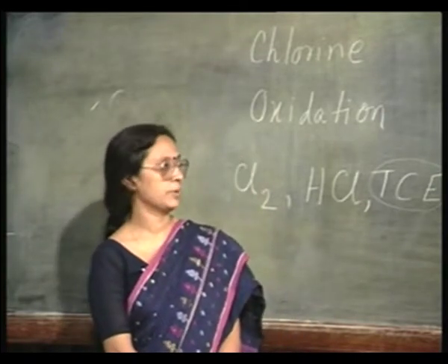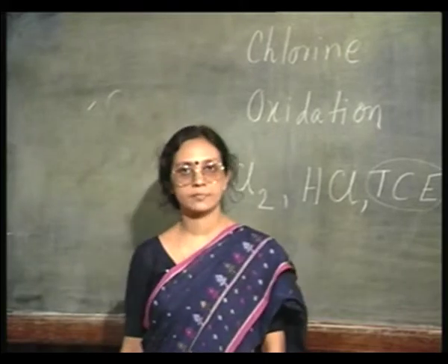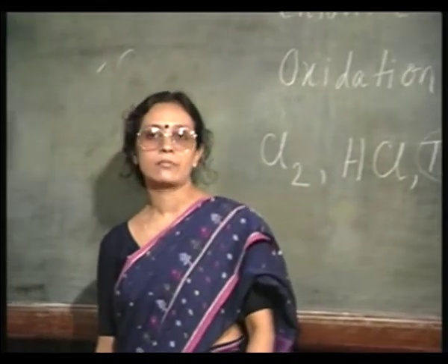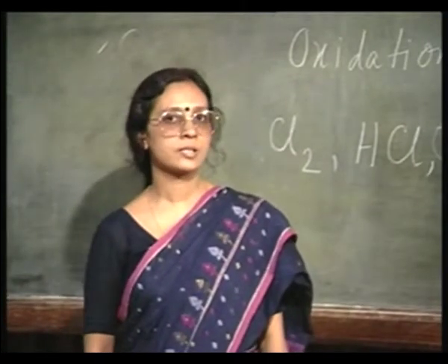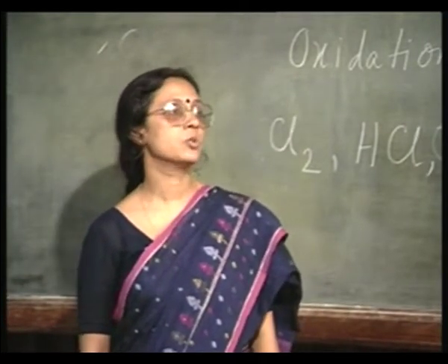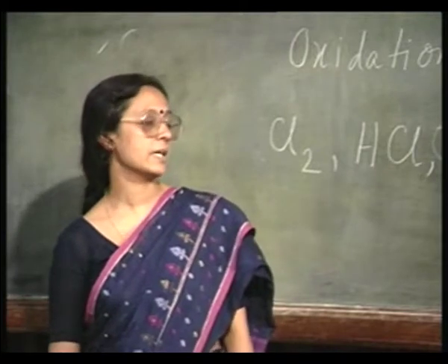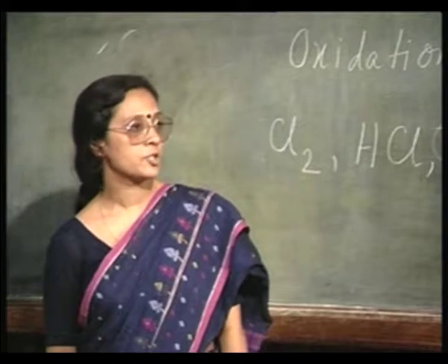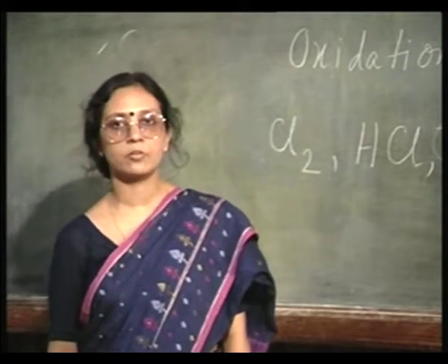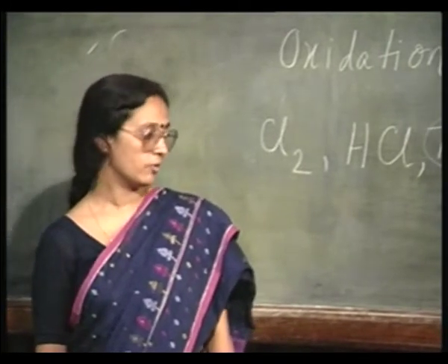How does it help in fixing the mobile ions? Well, chlorine can form sodium chloride and potassium chloride and thereby fix the mobile ions. The ions are no longer free to move inside the oxide, and therefore their detrimental effect on the electrical performance of the device is lost.